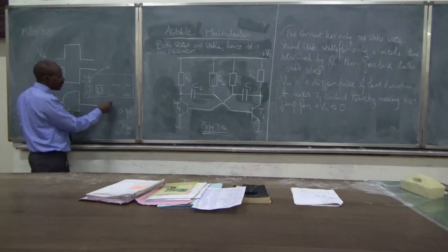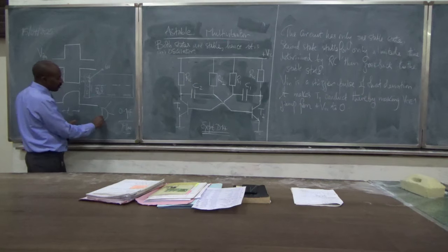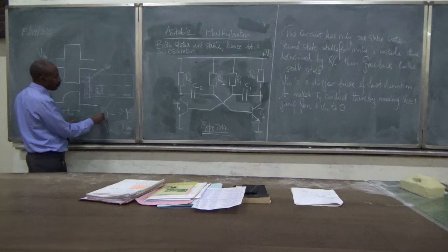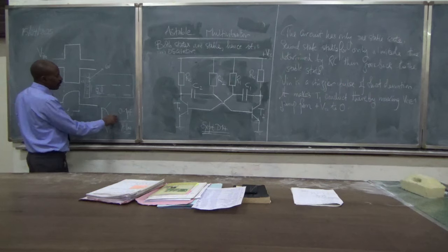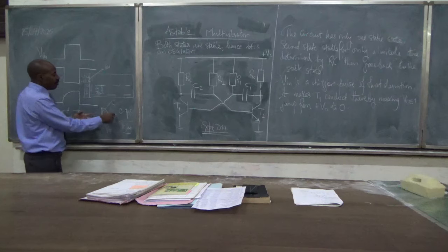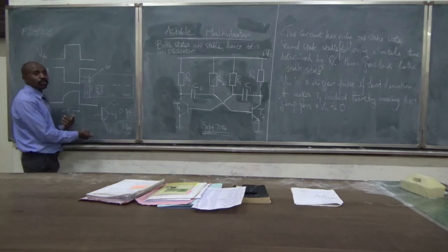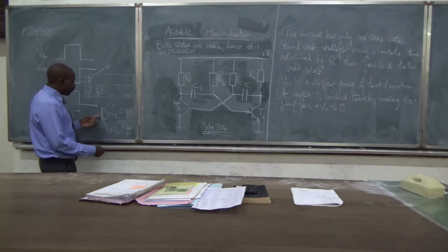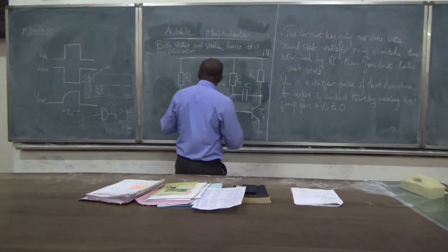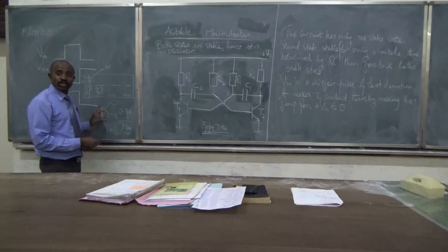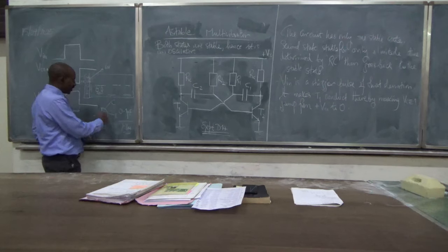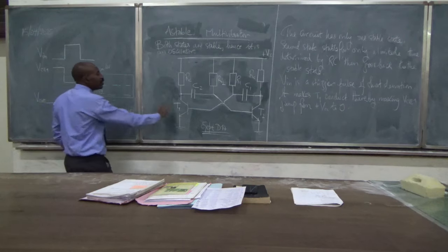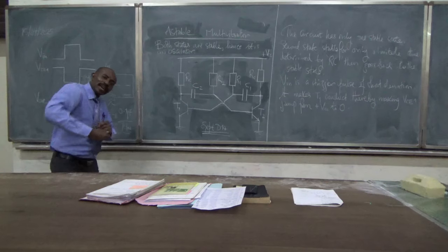And the transistor, I will explain in the lab. Once you make it stand like this, this will be the emitter, if this is the top view with the flat part facing this way. And this would be the base, and this would be the collector. The base could also be put this side. If this was the connection here, you can still place it the way it looks and make the leg go this side, not make it upside down, to make sure of the flat part.